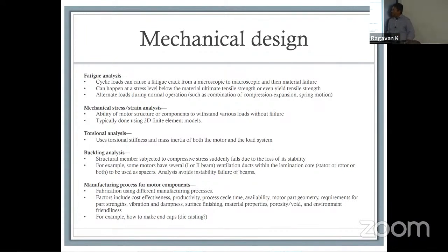Fatigue can also happen at stress levels where your tensile strength or yield strength is actually exceeded. And you can have scenarios in which you have an alternate load that you had not planned for. Let's say you have something as simple as changing the atmospheric conditions, where now all of a sudden what you had designed it for didn't account for the fact that you are at a different level of pressure, at a different temperature. Same things as what you might imagine for something like photovoltaics, right? You have to think about where is it going to end up. If you don't do that, that can create an extra load that was not planned in your original design.